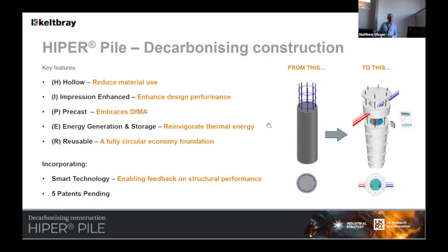And then the brainwaves start going into overload in terms of what you use the hollow core for: energy storage and generation, and we get around about a 60% enhancement in thermal conductivity, and the pile itself is fully reusable. So we come back to whether we need the pile in the first place. Well, if you can reuse the pile that was there in the first place, then you don't even need to talk about materials or factor of safety or anything else. So that, for the first time, really enables a fully circular economy foundation, with the ability to inspect the pile as it's in the ground and already in operation, and whilst the building's being demolished.